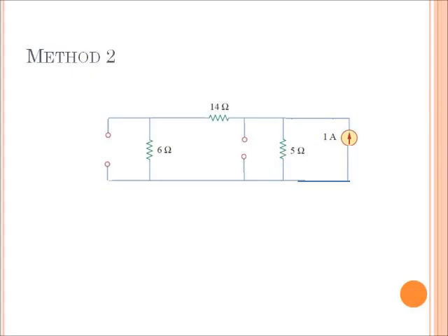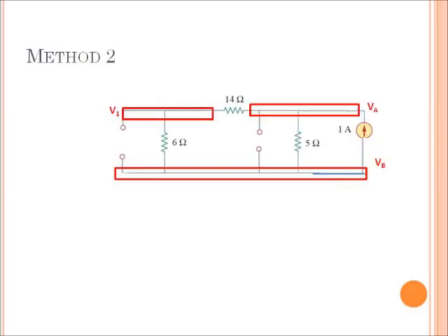If you choose a current source, you will have to solve the problem using nodal, and if you choose a voltage source, you will have to solve the problem using mesh. I wanted to use nodal, so I chose a current source, and I made it 1 amp to make my life simple. To solve this circuit using nodal, the first thing I need to do is to identify my nodes. We are going to set the bottom node, voltage V, to ground, making it 0. That just leaves two nodes, nodes VA and V1, to solve for.